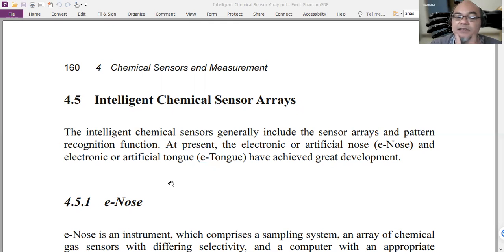Similarly with the gas sensor, which we discussed last week, selectivity is usually a problem because, for example, tin oxide sensors can be sensitive towards various chemical gases. They are sensitive towards carbon monoxide, and also towards carbon dioxide and nitrogen oxide, maybe, although with different sensitivity ranges.